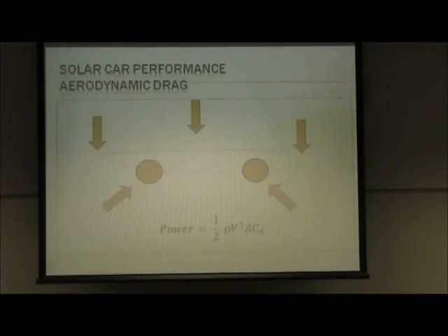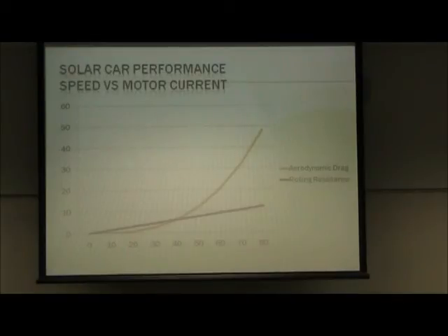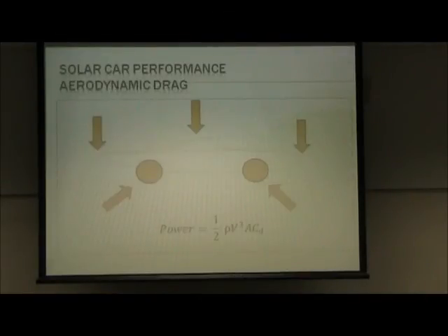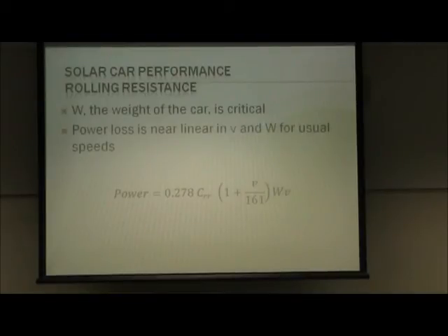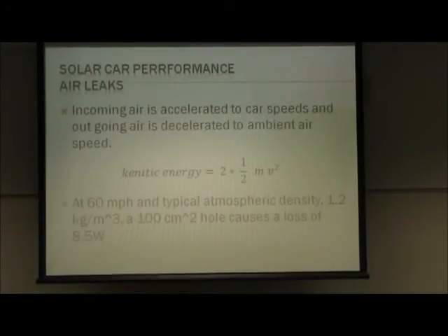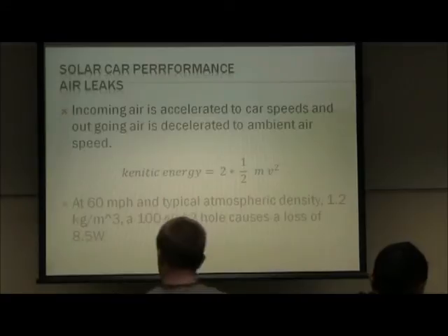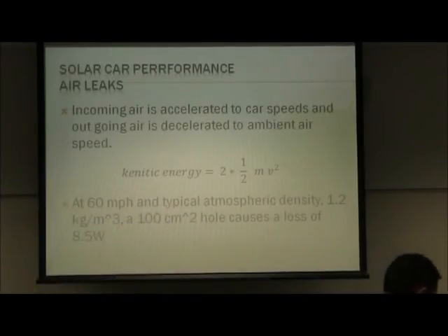So then we move back up to where on that chart? Whoa, way up there. So with headwinds, you have to adjust for that. You have to make that clear. That V was relative speed, not the absolute speed. That's why if you have a headwind, you've got to treat it as though you're having to drive faster. It doesn't hurt the rolling resistance, but it does greatly increase the aerodynamic drag and power loss there.